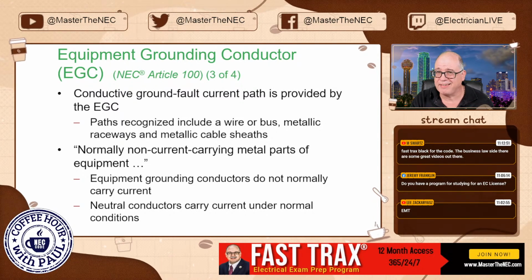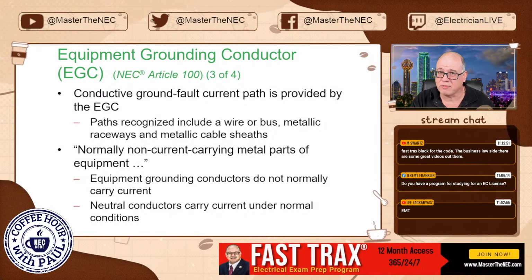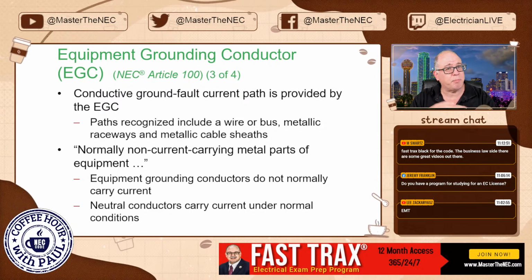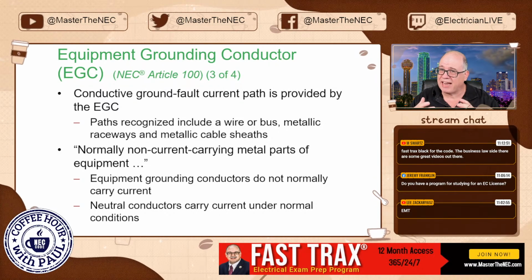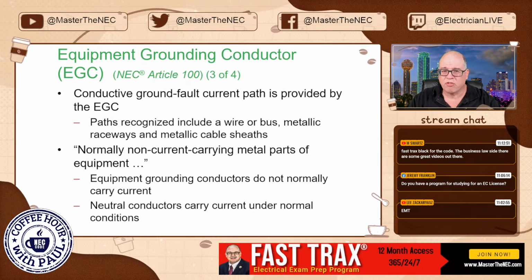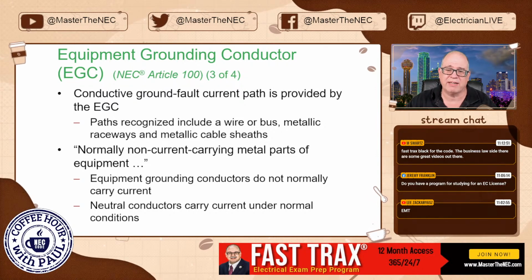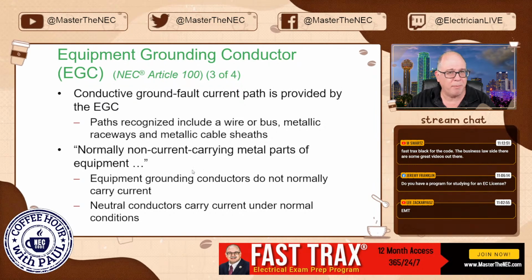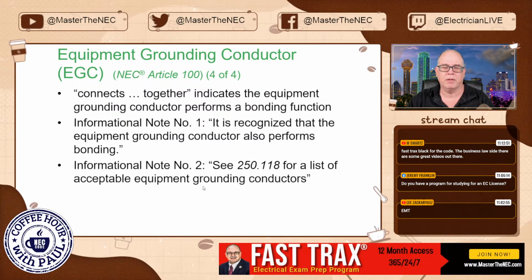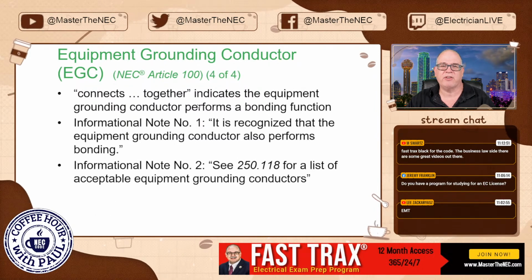It's not as simple as a DC circuit where you really just have resistance, okay? You have this rapidly expanding and collapsing magnetic field in an AC current, and all of that can have a negative effect on current flow. So again, we always have current traveling in the neutral. So remember, you can get just as shocked from a neutral. That's why we don't make connection to metal enclosures downstream.